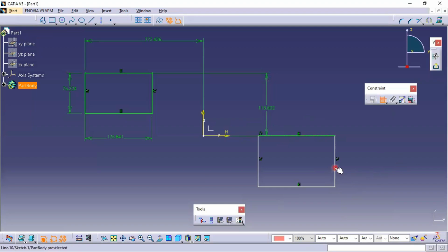First, what I do is, I will define its size. So its height and its length. Once I define height and length, size is over. Second thing is that I have to give reference location from vertical and horizontal. As it is already on the horizontal axis, no need to give from the horizontal. Only take vertical to any of the 4 points. See, right? So your sketch is constrained. Clear?